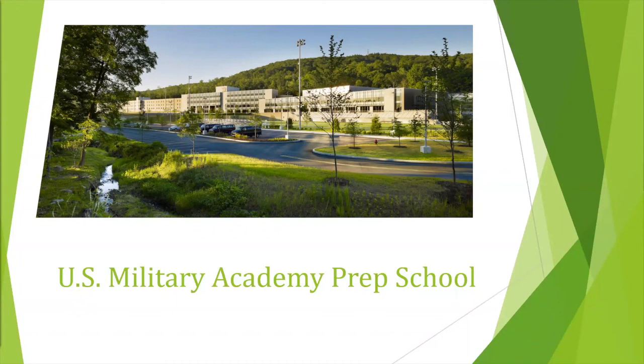So what we had to do here, and you can see in the forefront, we actually had to relocate a stream. And what we did was daylight this stream and make it larger so that it actually could handle more of the runoff and the detention from this site. Like I said, the football field, which unfortunately you can't really see in this picture, which is off in the bottom, that was over the landfill.